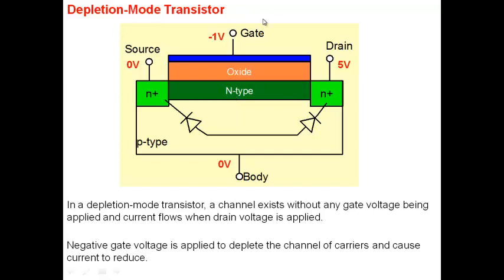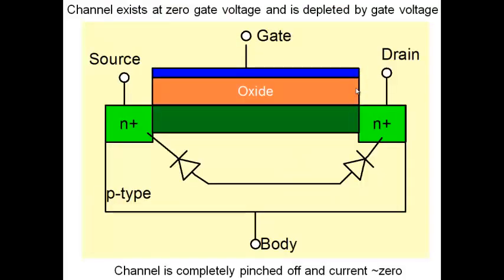So what happens is, at 0 volt then, a current flows between source and drain. If I apply negative voltage, note we already saw what negative voltage will do, which will repel the electrons from the surface here. Will repel the electrons, and therefore the conductivity of n-type will change, will decrease, and the current will decrease here. Okay. So let's see that thing in more detail here.